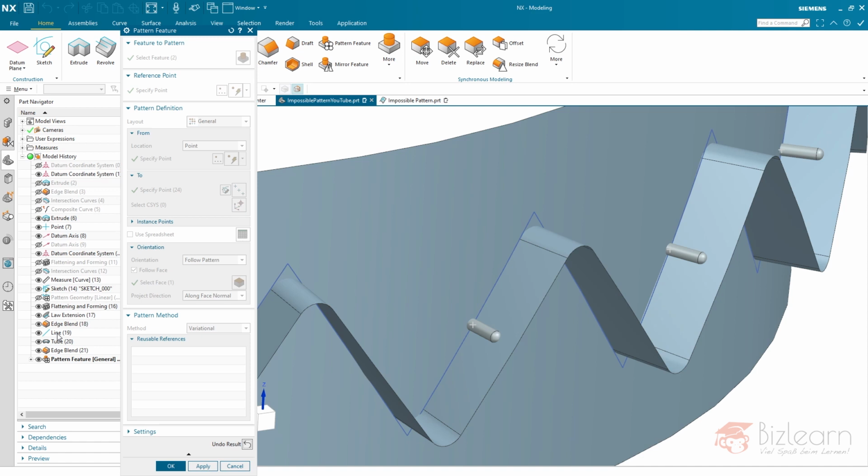There needs to be a relation from the line to this surface in order to work properly. And that's one of the reasons why I was not creating a sketch. I mean, the sketch can be positioned on this surface. As you did see here, by using the datum coordinate system and the datum axis, the second one has a relation to the surface, as you might remember.